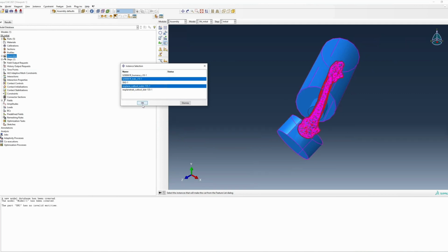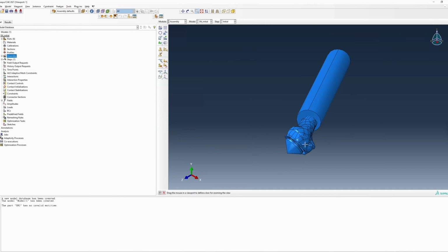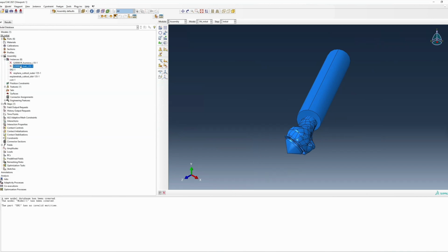By subtracting the trabecular bone model from your cortical bone model using a Boolean subtraction, you'll be able to achieve a thin cortical shell without worrying about any kind of work in Mimics, as the reducing and wrapping features of Mimics are sometimes a little bit difficult to work with.